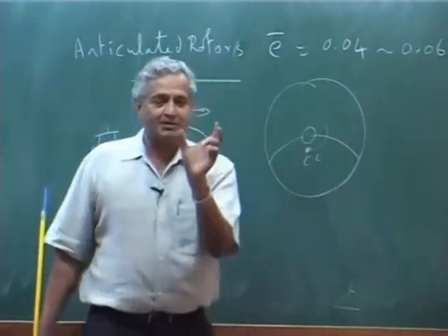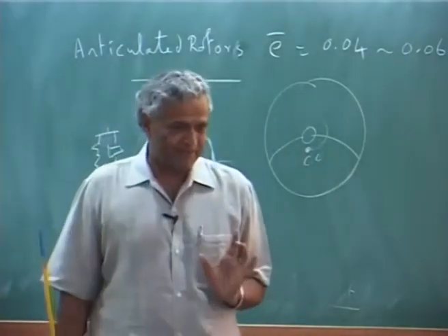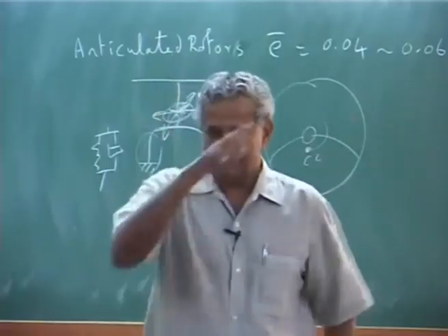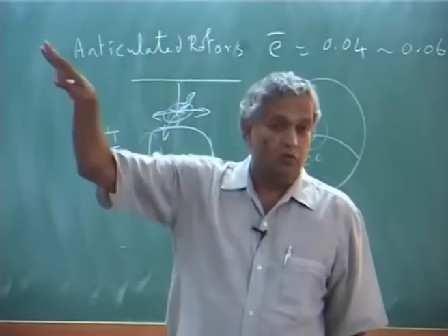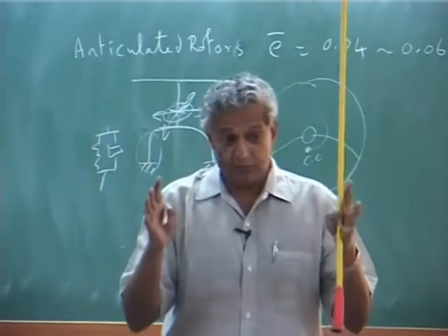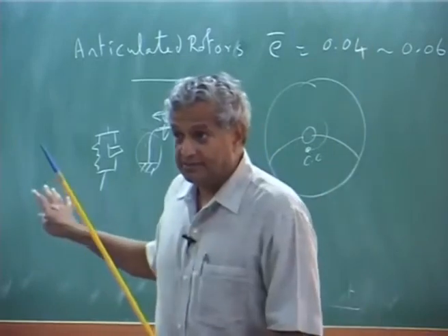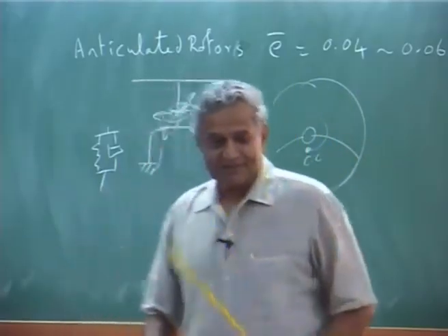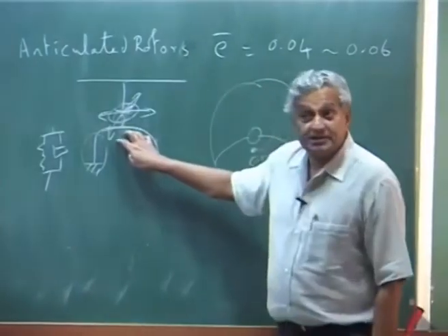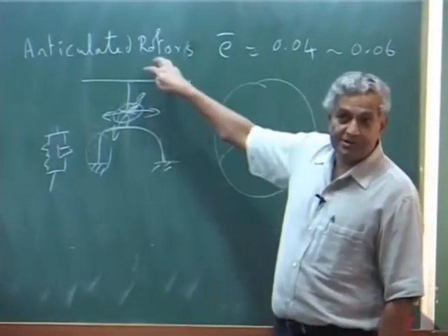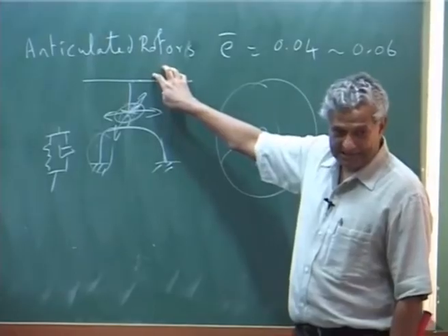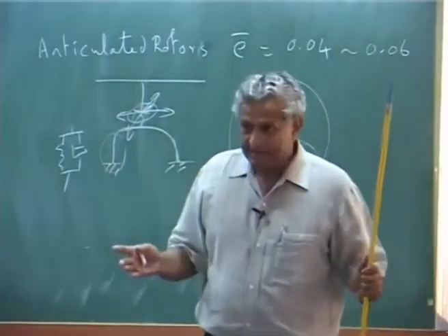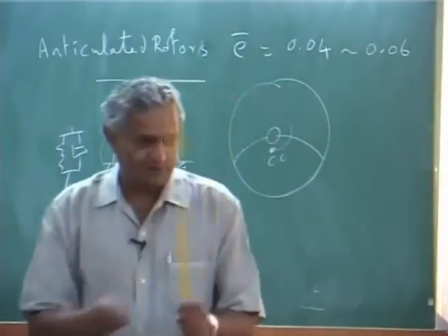See, this happens at a particular combination of frequency matching, okay. So, you have it as a stiff in plane range. If you draw the diagram of actually how the frequencies go, the frequency of that full dynamic system, not just a lead lag alone, please understand. But there is something more into that, because one is a non-rotating frame, another one is a rotating frame, okay. Now, each blade will be rotating. So, you have to have each blade's equations, then they are getting affected by fuselage motion.